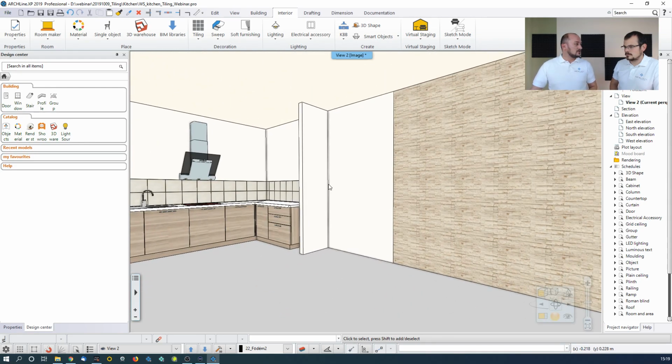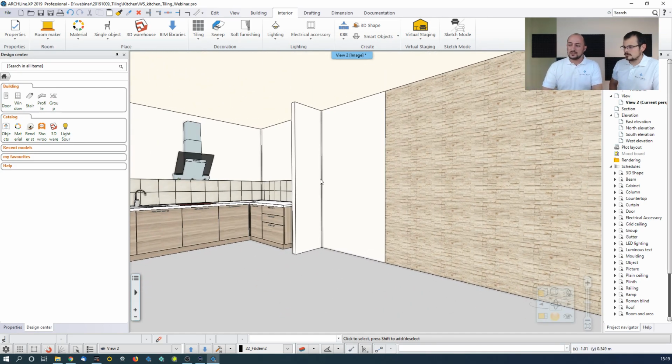coloring or wallpaper or something like that, I mean adding literal textures, then it will be the feature that you want. This is the same thing that we will apply soon. We will talk about that when we talk about carpet flooring, parquet flooring, and so on. The thing that we need to decide when we are about to cover a surface is whether we would like to calculate the amount of tiles, in that case we will go with the tiling, or we are only curious about the look and the area that is covered, in that case we will go with the background area.